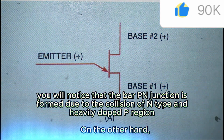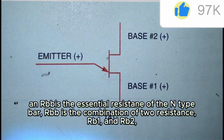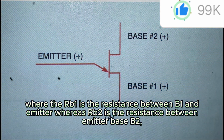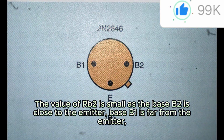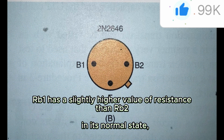RBB is the essential resistance of the N-type bar. RBB is the combination of two resistances, RB1 and RB2, where RB1 is the resistance between B1 and the emitter, whereas RB2 is the resistance between the emitter and base B2. The value of RB2 is small as the base B2 is close to the emitter, while base B1 is far from the emitter. RB1 has a slightly higher value of resistance than RB2 in its normal state.